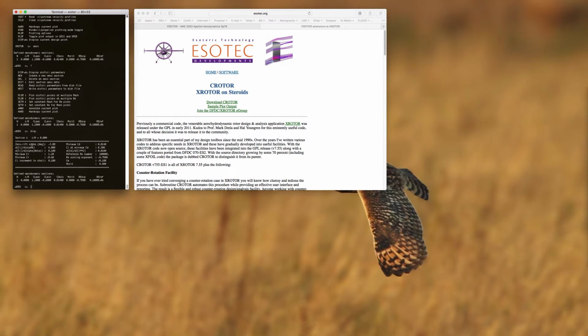Things such as the zero lift angle of attack, the DCLD alpha in radians, the value of DCLD alpha at the stall angle of attack, maximum CL, minimum CL, CL increment to stall once it gets to the stall angle, and then some other basic drag parameters as well. So this will allow you enough information to essentially construct what that lift curve slope and drag polar looks like for that particular airfoil section.